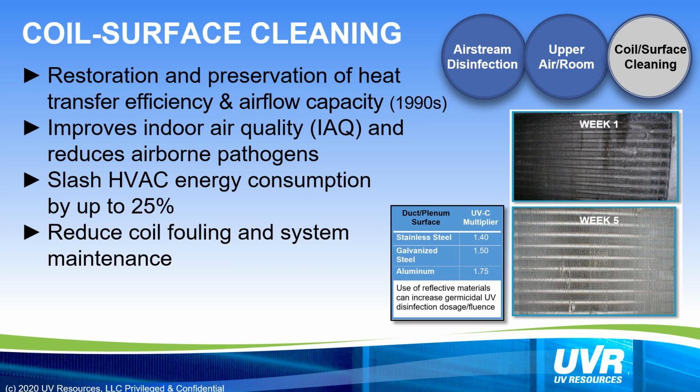So in a very short period of time, you start to see things happening with these coils. You start to see a lower pressure drop, you start to see an increase in airflow, and you get a better heat exchange efficiency.